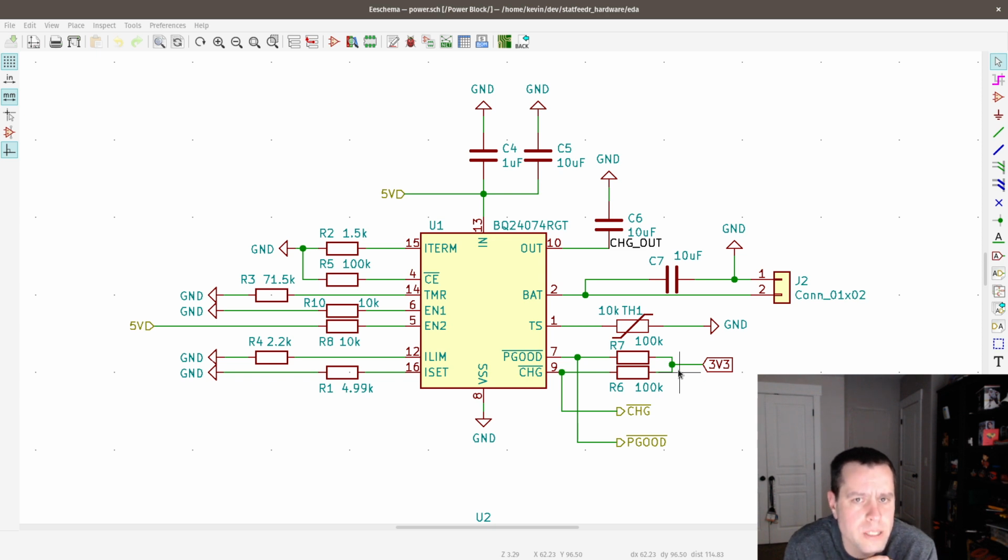It normally doesn't brown out and then never come back on ever again. So my creative way, given the hardware that I have to work with: the ESP32 has a code when it boots up that tells me the reason I reset. Somebody pushed the reset button, somebody reset in code, it crashed. It has a reason code for the reset, and one of those is that I browned out.